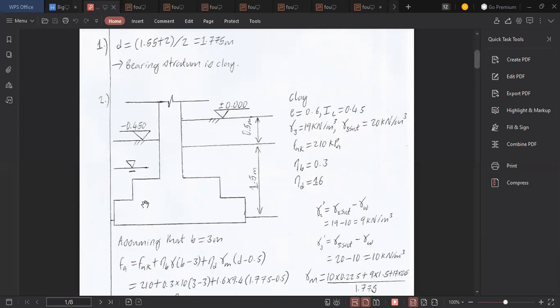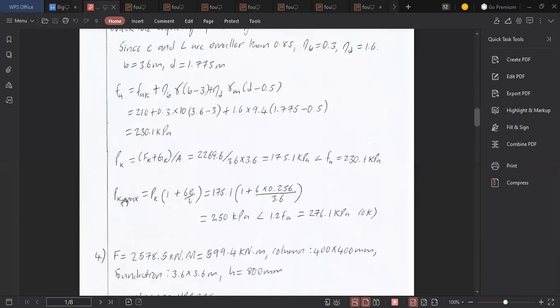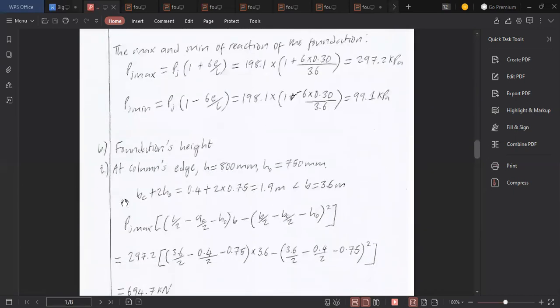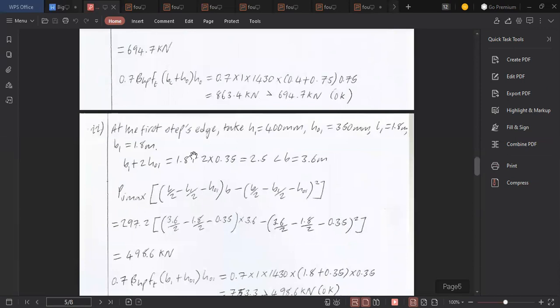Now I want to check from here to here, which is about half, so 400. We're here, and then also the dimensions of that step, how big it is. We make assumptions first, so take the height of that to be 400. The effective height is 400 minus 50, which is 350.